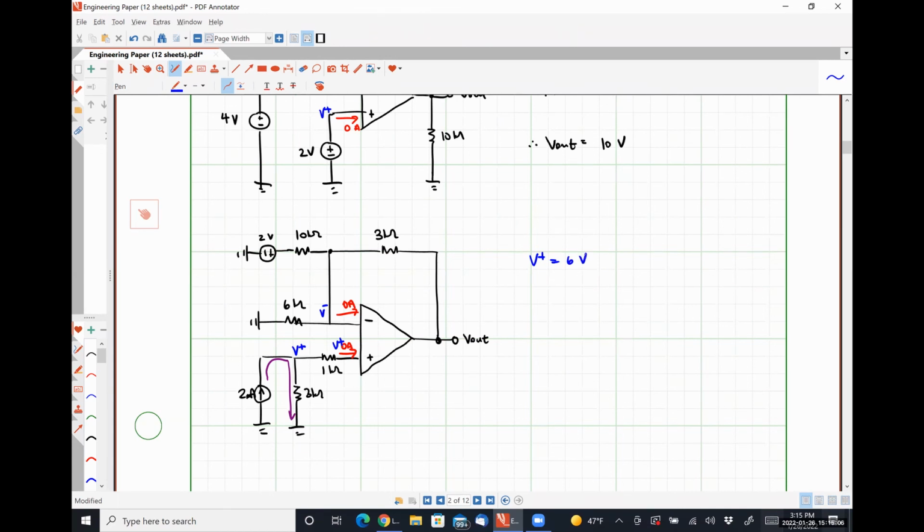We got that just using Ohm's law, nothing remotely fancy or anything, right? Simply by recognizing none of that 2 milliamps of current can branch off and flow into the input terminal. So all of it has to flow down through the 3 kilo ohm resistor. Okay. So now we're going to apply Kirchhoff's current law at the inverting input terminal, which means we're going to add this current and this current together and solve for V out. Kennedy, could you help me with this equation?